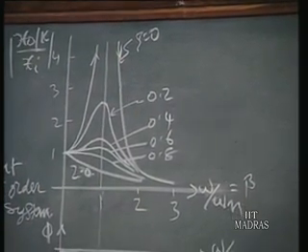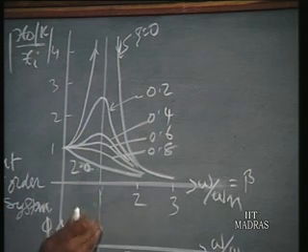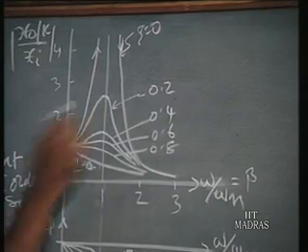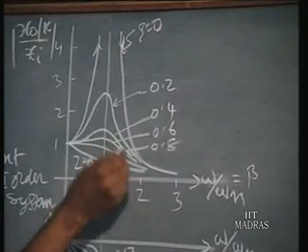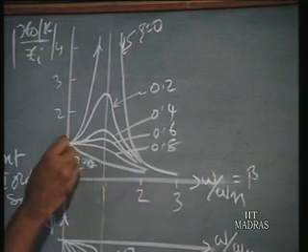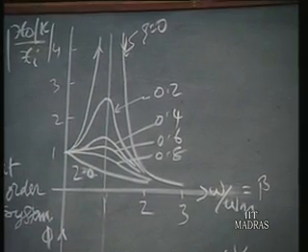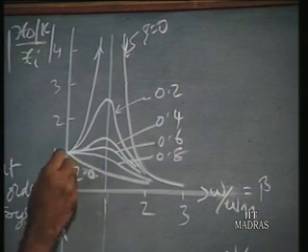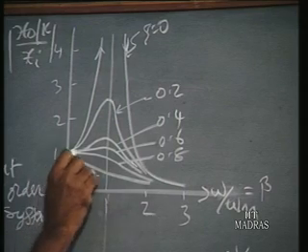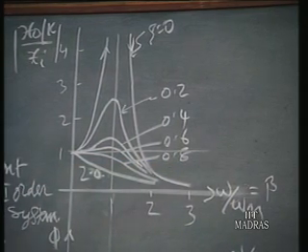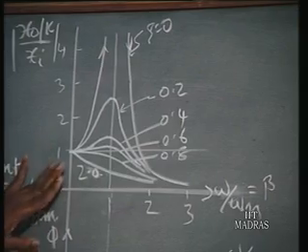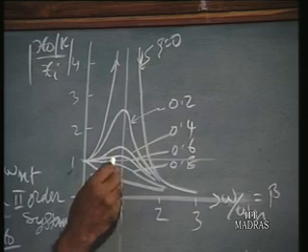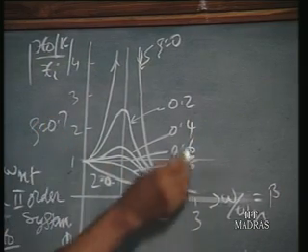And when ψ is increased from 0, you will find the maximum amplitude occurs when ω is equal to ωn. That is what is depicted here. But between 0.6 and 0.8, say ψ equal to 0.7, as you have learnt in the step response, 0.7 is a very ideal value. Similarly here also, around 0.7 you have the ideal value, it should be around 1. So xo by k by xi should be equal to 1. That is perfectly proportional conditions without any error due to the dynamic conditions. That is achieved when ψ is around 0.7, between 0.6 and 0.8.